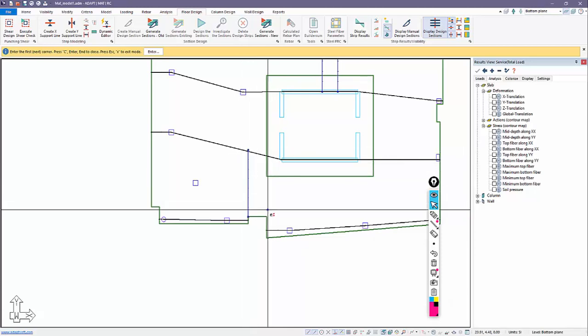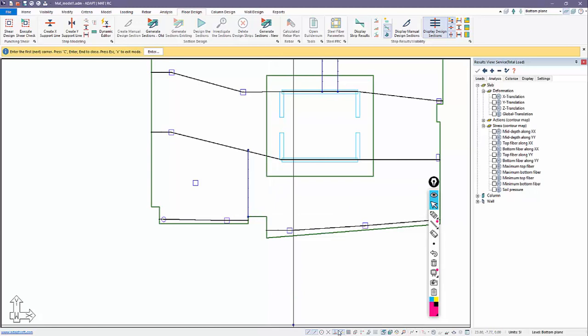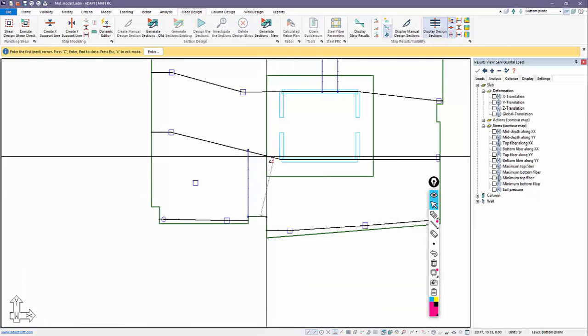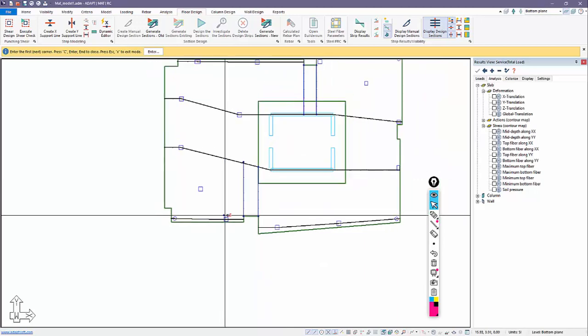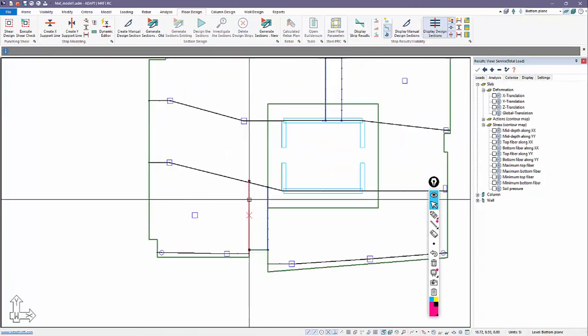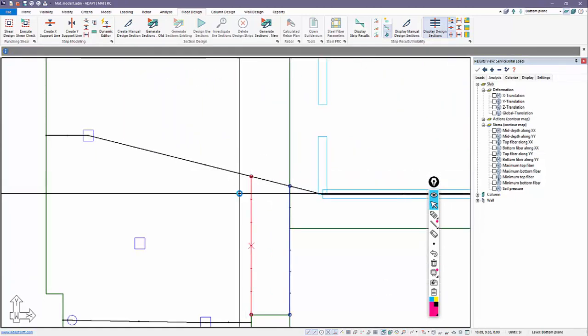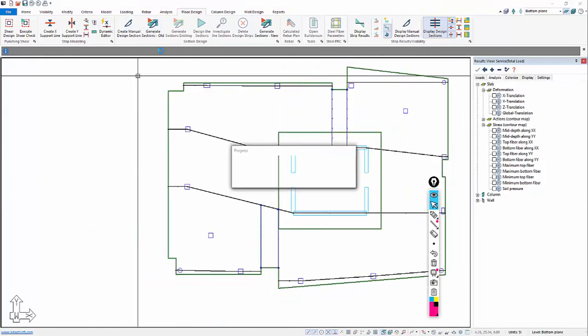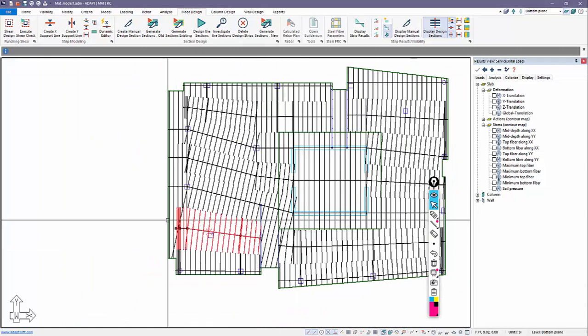So we'll create a splitter there, and then one more splitter. We'll use snap to intersection, something like that. Okay. I'm going to bring this back so it intersects there. And we'll go ahead and generate these again. And now you can see this cleanly stops at this location. Same thing here, that stops at that splitter. This stops right at the splitter, and that happens here also. So we'll use these strips.